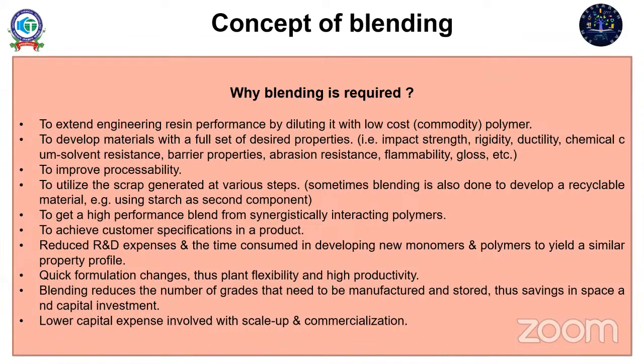Yes, we are just diluting it to have a low cost product, for cost reduction purposes. If you see automotive, there are some parts which are required on the exterior side. For exterior parts, we cannot compromise on the properties or dilute the performance of the engineering resin, right? But in the case of interiors, where engineering polymers are being used, we can dilute some of the performance of the engineering resins.